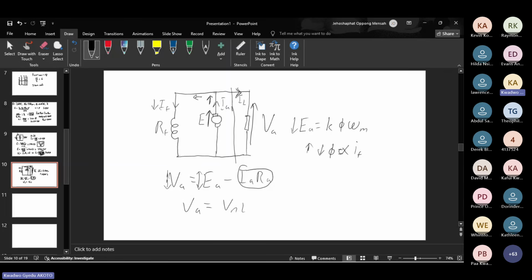This is done when the voltage VA is to be used at the site of generation. But for over compounding, we increase our IA to such a high level that our terminal voltage VA becomes greater than our no load voltage, right? And this is done when our voltage being generated is to be transmitted.